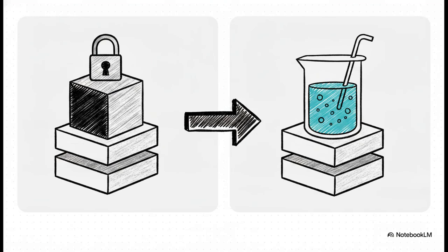The solution to that cliffhanger is honestly shockingly elegant. We just completely get rid of the rigid metal gate. Seriously. In a standard MIS device, that metal gate's work function never, ever changes. But in an EIS device, which stands for Electrolyte Insulator Semiconductor, we swap the M for an E. We replace the metal with a dynamic reference electrode immersed in an ion-sensitive test solution.